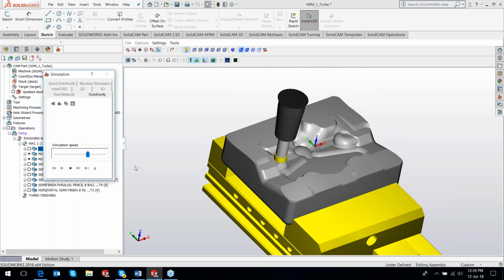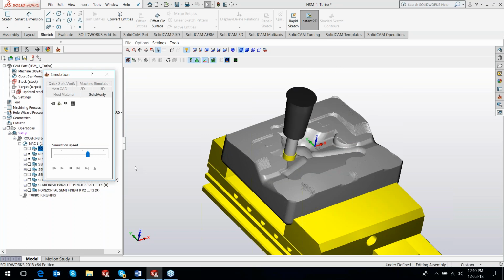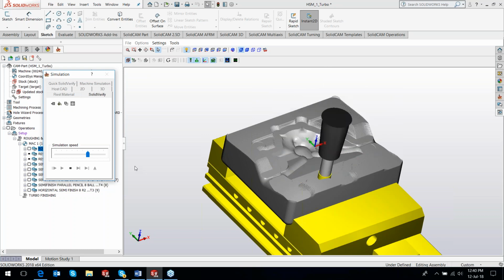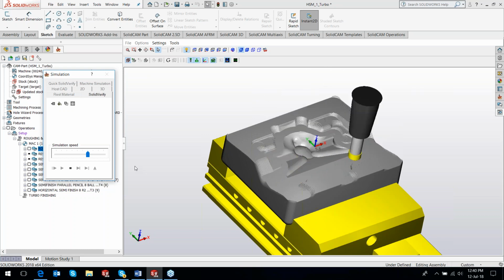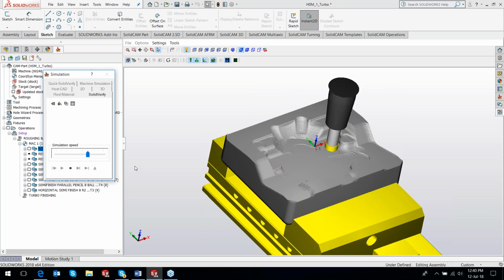No more air cuts. It'll directly cut the material wherever it finds it. It's automatically taken the high point, and it's cutting exactly from the high point. A very important and an interesting functionality that we needed, and it's now in 2018, definition of stock by offset.